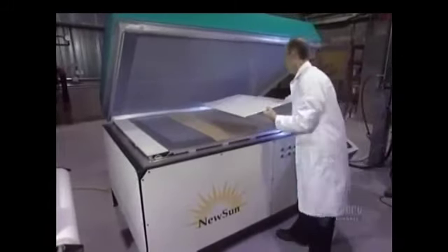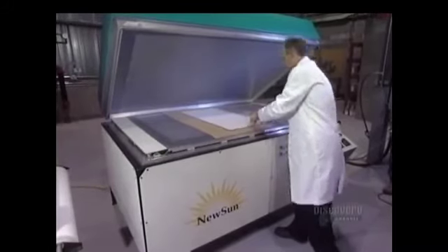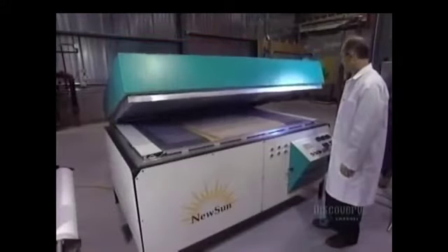Superposing of parts forms a laminate which increases the rigidity and solidity of the panel. Finally, a sealing film is applied to protect the module. To laminate and stiffen the solar panel, it's placed in a heated oven from which air has been vacuumed out. The panel will cook at 80 degrees centigrade for 15 minutes. The oven hermetically reseals to proceed with the vacuuming out of air.